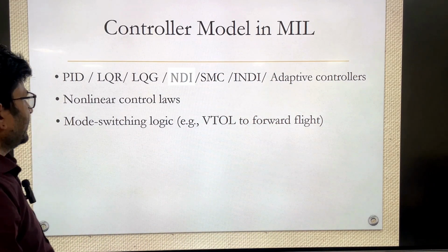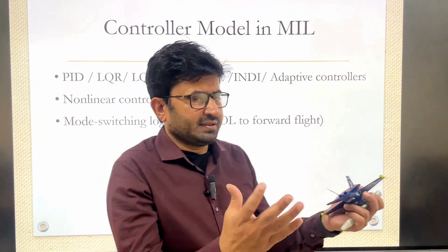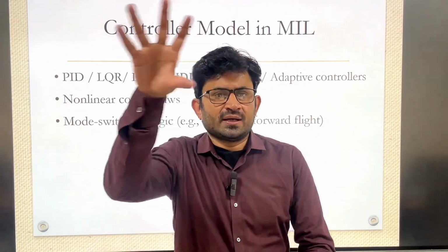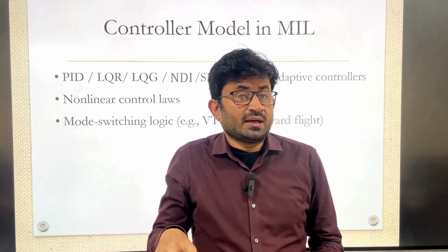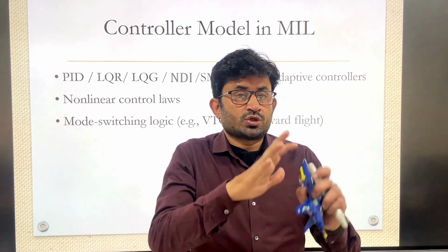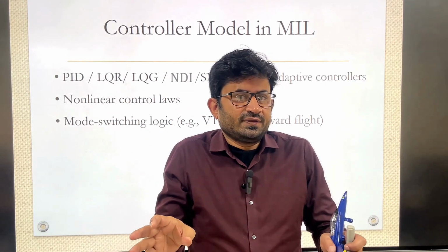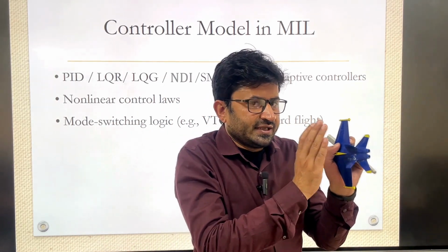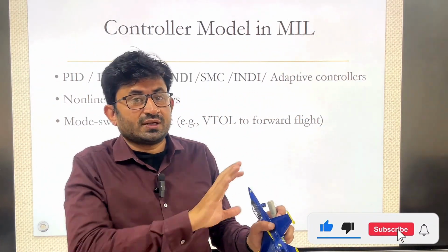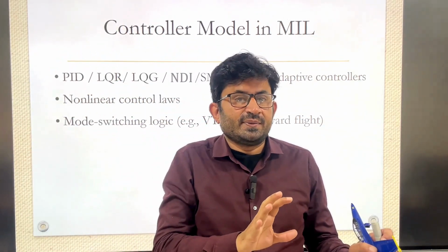And finally, when you have designed the controller at different operating points and you combine all the controllers, the gain can be scheduled based on the speed squared or dynamic pressure. So the overall control architecture, even though it is linear at one particular trim point, since so many controllers you have designed, will be non-linear only.